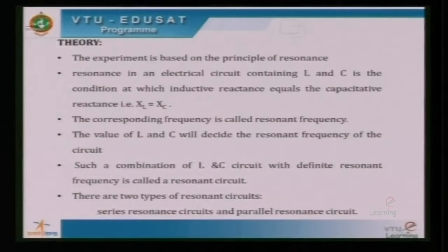Resonance in an electrical circuit is nothing but the condition at which the inductive reactance equals the capacitive reactance. Inductive reactance, represented by XL, is directly proportional to the applied frequency and is nothing but the impedance offered by the inductor to the flow of AC current. When XL is equal to XC, the corresponding frequency is referred to as the resonant frequency.